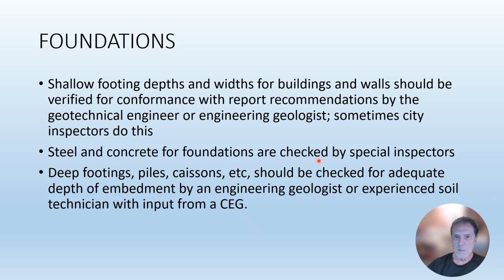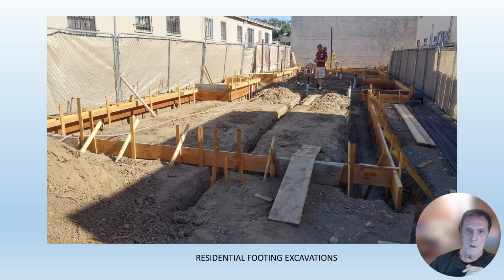Steel and concrete are checked by special inspectors. Deep footings, you want to check those for adequate depth of embedment into compacted fill or into formation. Okay. So here's a simple photo of a simple residential structure with footing excavations having been dug out.